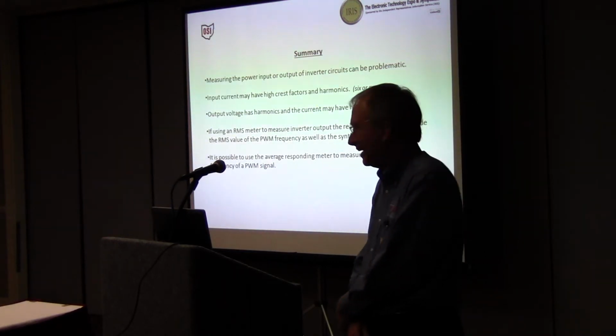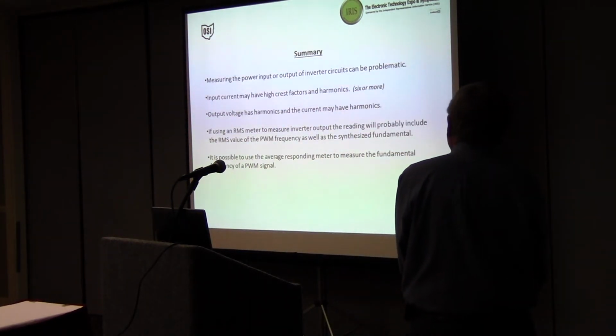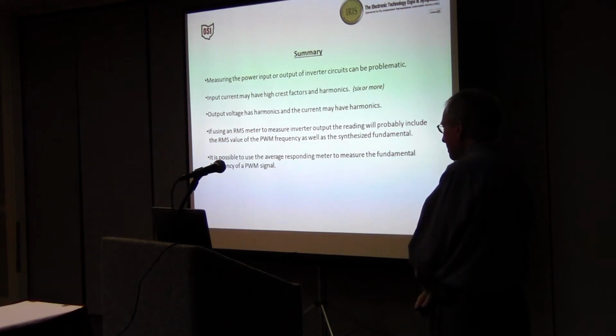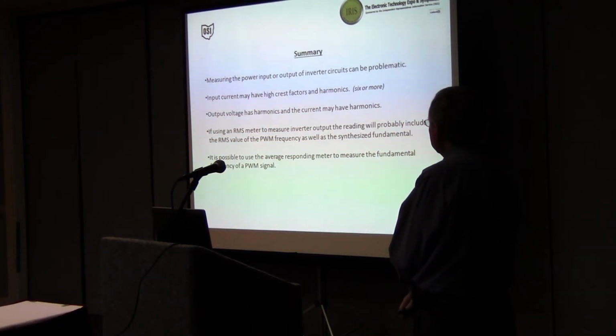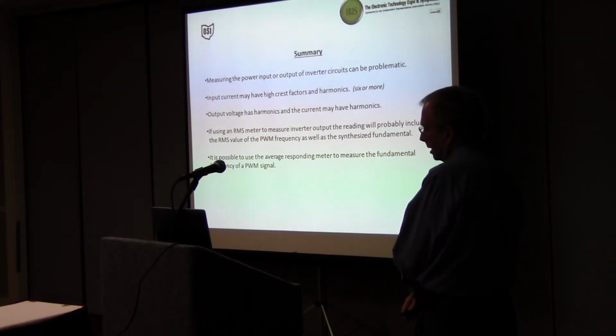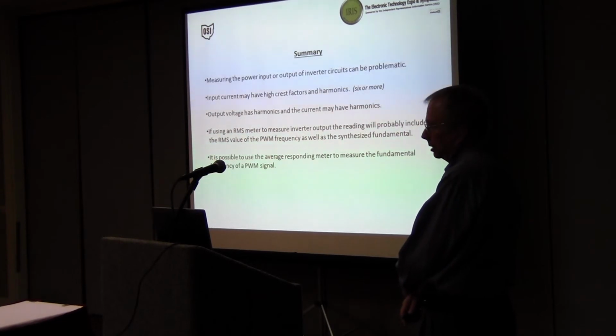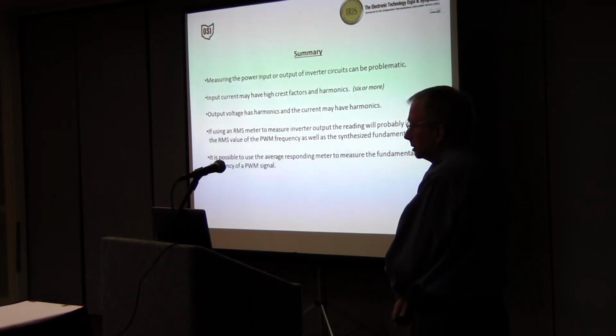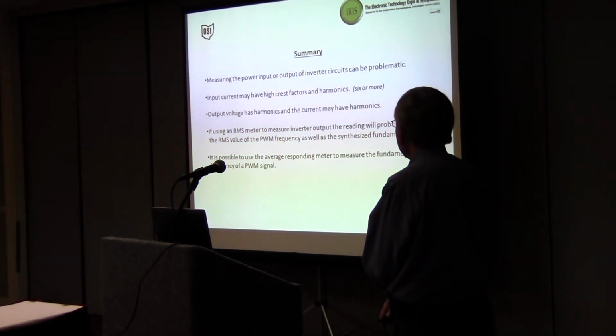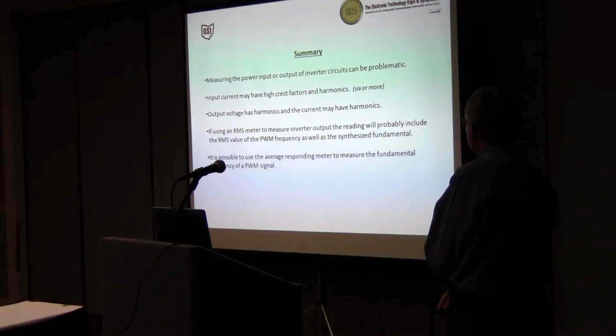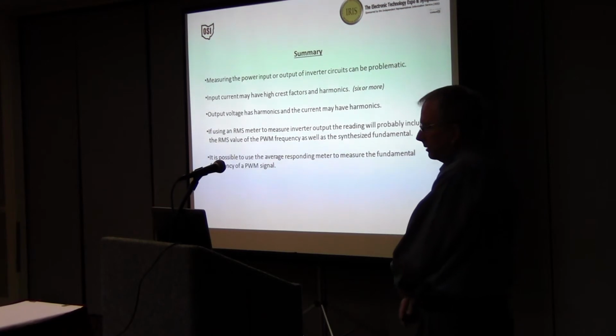I'm at my summary slide. Again, what I was trying to present in this presentation was that measuring power can be problematic when you're trying to measure the power on the input side or the output side of an inverter. Currents can have very high crest factors, and I said may have harmonics.